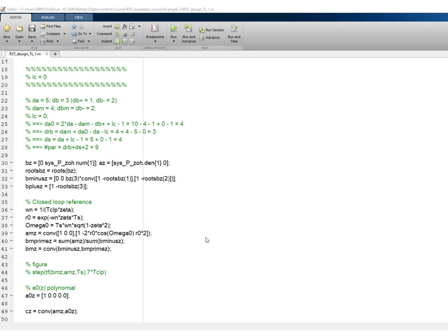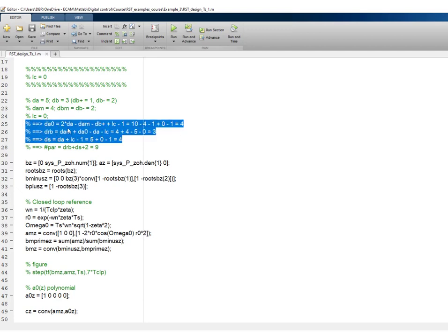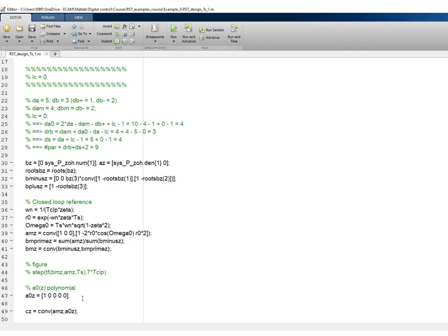So again, what we have done so far is common for a design with or without integrator. So from now on it changes. We'll start without integrator. Lc is going to be 0. So now you can obtain the degrees. The degree of the observer polynomial is 4. Here it is. Here again we have chosen to put every root at the origin, but this is not necessarily so.